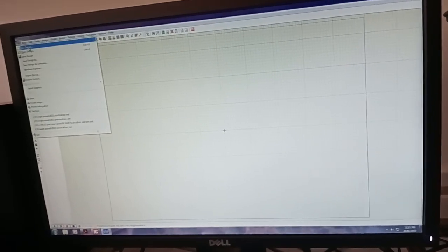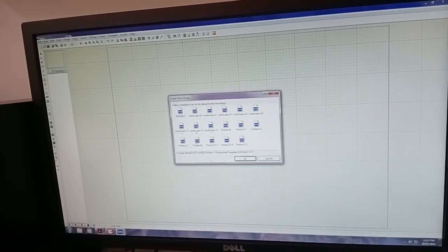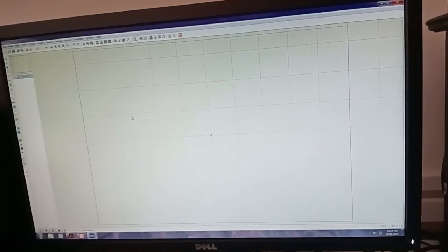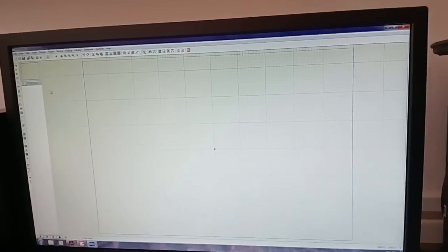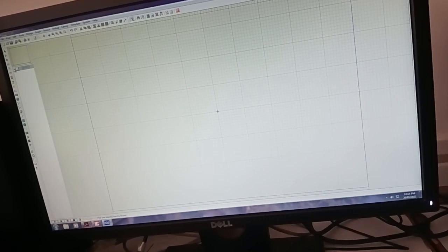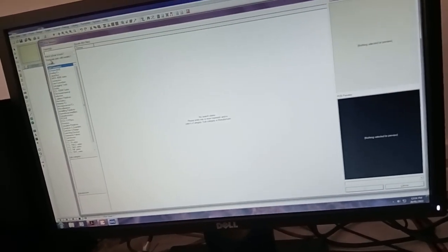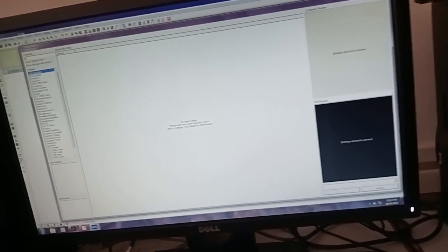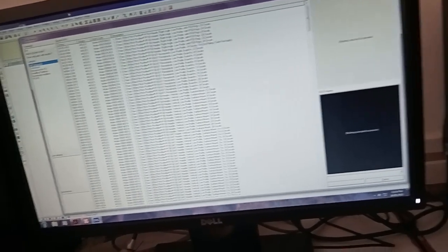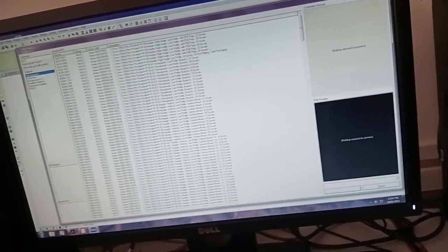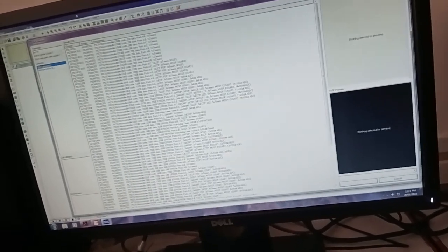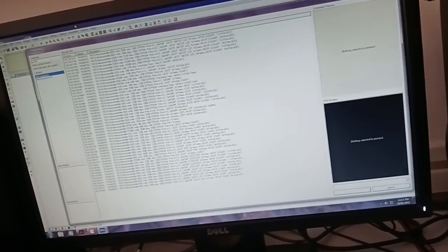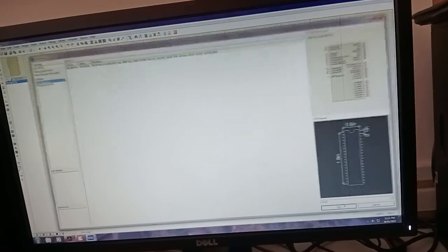Firstly, you select the file and then new design. In that new design, by default the design is saved. So here you choose the P. Firstly you use the PIC microcontroller. You know that the series of the PIC microcontroller is 16F877A. We use the PIC 16F877A. Choose this microcontroller here and then select OK.